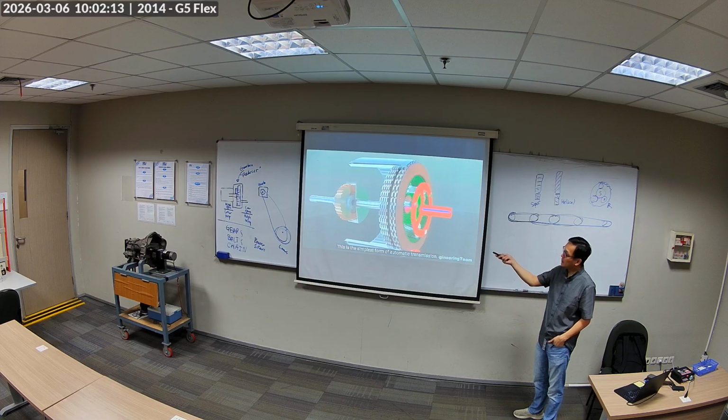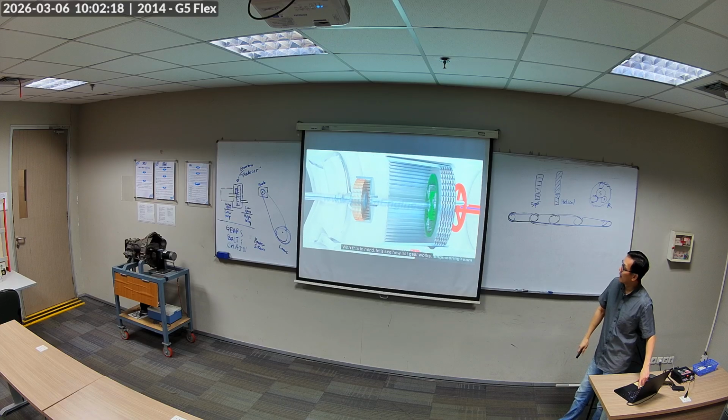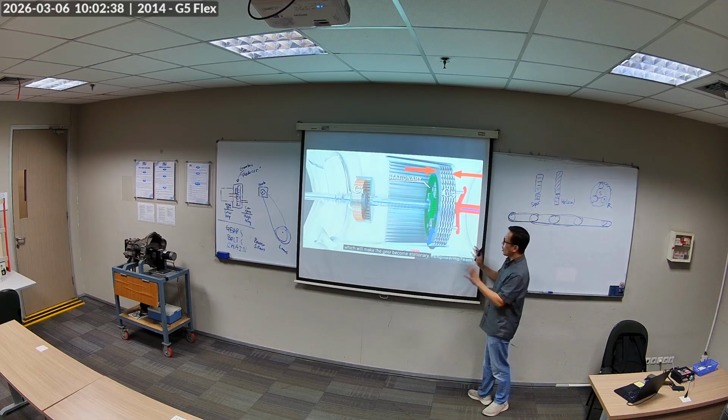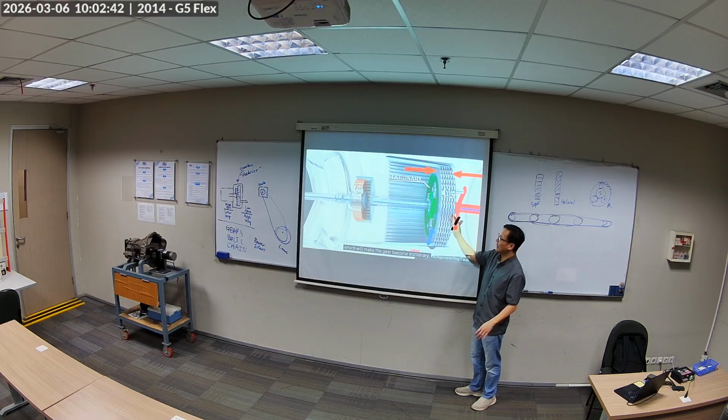Again, we have this, which is the simplest form of an automatic transmission. With this in mind, let's see how the first gear works. If the first clutch pack is applied, the input shaft will connect to the intermediate shaft. On the other hand, if the second clutch pack is applied, the ring gear will connect to the case, which will make the ring gear become stationary. Okay, so this is the first combination. You engage C1 and C5, and you can see there is more.